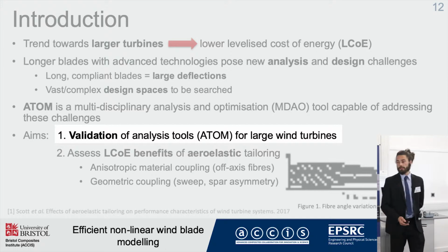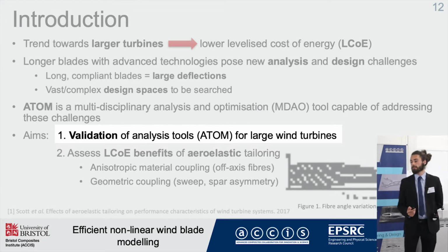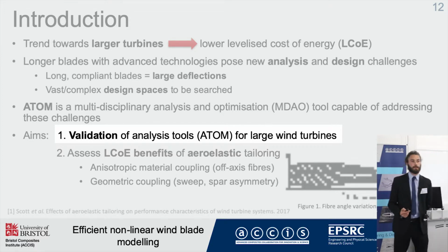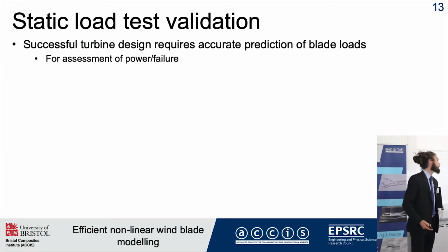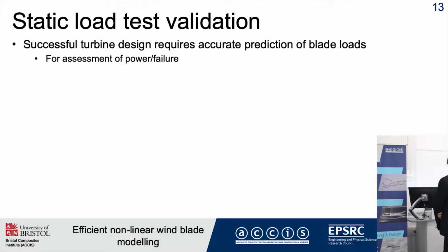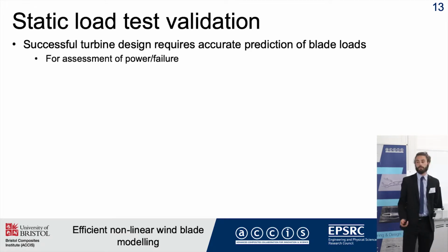So what I'm mainly going to talk about in this presentation is the validation aspect of the PhD. We did a validation study of a static load test of a large turbine. So, successful design requires that we accurately predict the loads during the design phase. That's for assessment of power and assessment of failure.